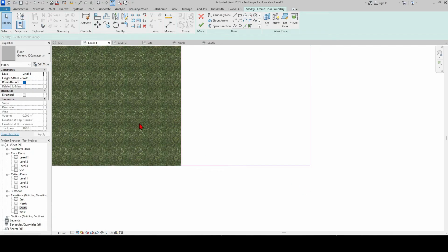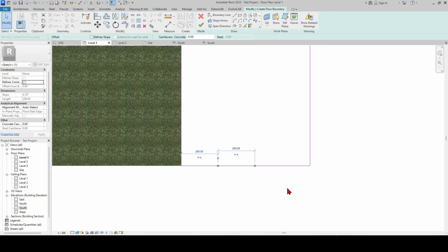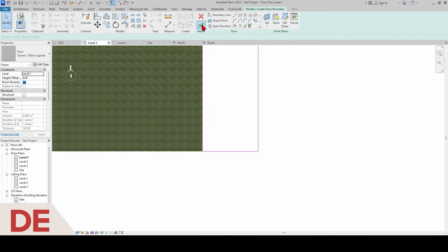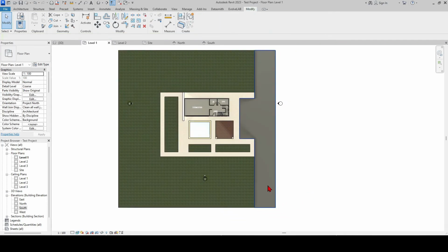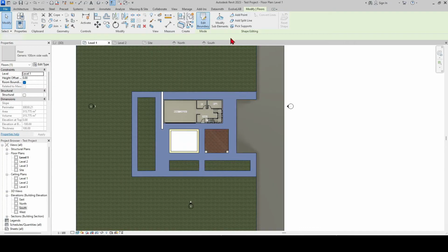Remember, if you select from the right, it selects everything it touches, and if you select from the left, it selects what it contains. Once you have selected the overlapping line, delete it. Let's draw the sidewalks on the road.